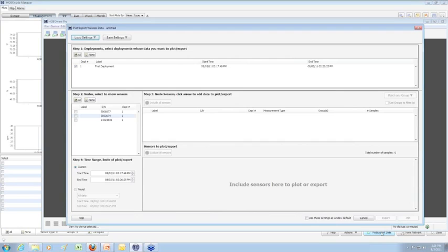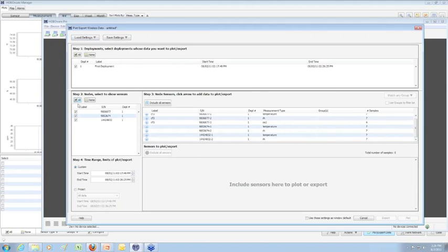What this does is it really allows you to combine and mix and match. Similar with the standalone data loggers, essentially you would download a bunch of different data files, and then you'd have to either combine those within HOBOware Pro or Excel. What we're doing here is basically running a query against the database. So the first thing that we want to do is select which nodes we want to get information from. So we'll just check those here. And then we want to look at our time frame.